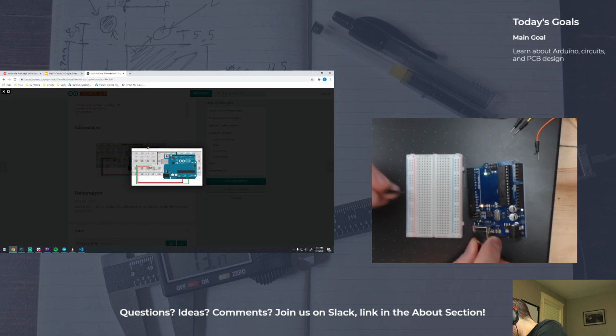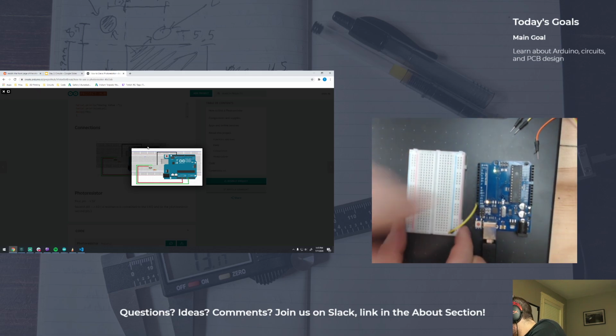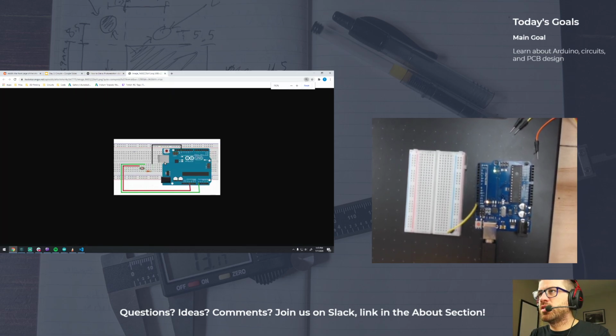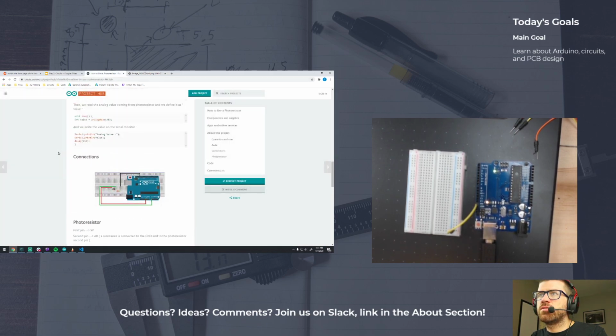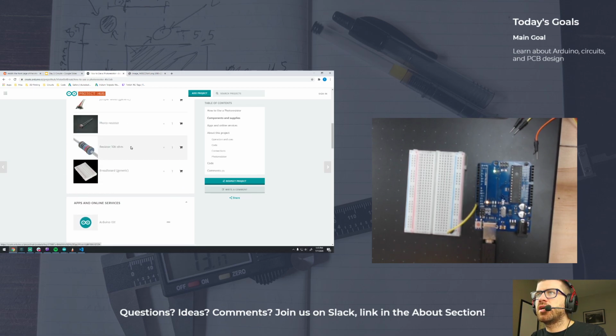So it was pin 4 down was ground, so we'll bring ground in, connect that to our board. And then, man, I wish I'd given a better, let's see if we can zoom in on this thing. Okay, still blurry, but at least we can kind of see where these wires are going now. So this ground wire comes in, and we can see that this symbol here is the resistor, and then over here we have the photoresistor, and then we have some other wires which connected on the other side.